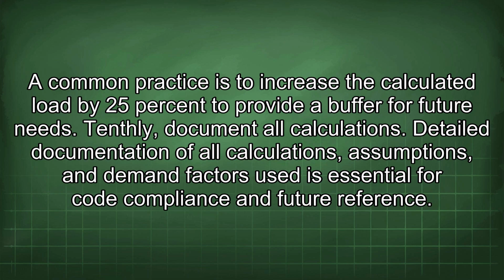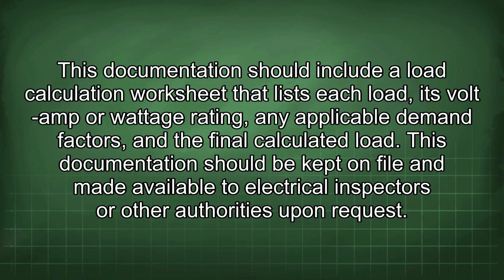Detailed documentation of all calculations, assumptions, and demand factors used is essential for code compliance and future reference. This documentation should include a load calculation worksheet that lists each load, its volt-amp or wattage rating, any applicable demand factors, and the final calculated load. This documentation should be kept on file and made available to electrical inspectors or other authorities upon request.